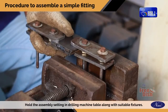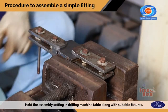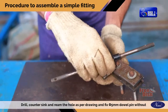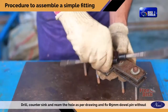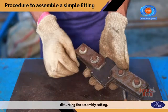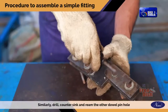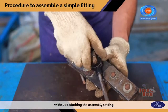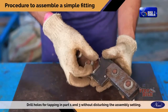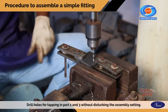Hold the assembly setting on the drilling machine table along with suitable fixtures. Drill, countersink and ream the hole as per drawing and fix a diameter 5 mm dowel pin without disturbing the assembly setting. Similarly, drill, countersink and ream the other dowel pin hole without disturbing the assembly setting and fix the other 5 mm diameter dowel pin. Drill holes for tapping in parts 1 and 3 without disturbing the assembly setting.